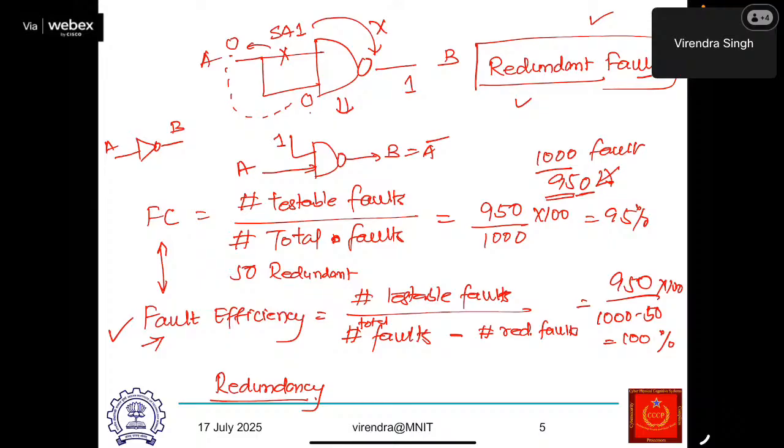So redundancy may come knowingly or deliberately. In this case, we know that there is a redundancy in the circuit, but that makes my effort less. It can make the layout more structured, where it needs less effort to lay out the chip. Otherwise, I need to design two circuits and then make the layout of those two circuits.